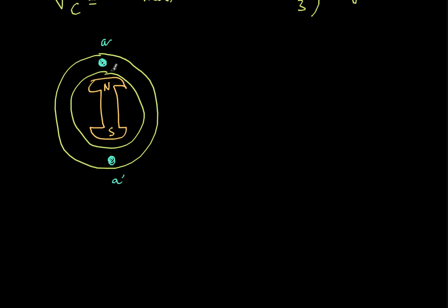So let's continue. If I define this as my axis, and let's say this pole is rotating like this. Physically, let's say this is 90 degrees and this is 120 degrees. At this location, I'll keep another coil, B dash. The axis of A dash and the axis of B dash are separated by an angle of 120 degrees. Then a further 120 degrees from here, it will come somewhere here. I'll call this C, and this is the other end, C dash.